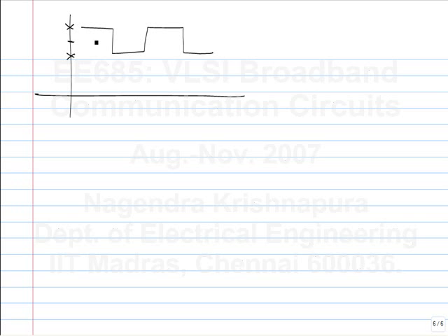Okay, that tends to also increase the error. So what you do is, in this case, you would rather keep the coefficient constant, and you achieve that by averaging this sign of e and sign of x. Only if sign of e and sign of x is constantly positive, that means the accumulated value will keep ramping up and hit a certain threshold. Only if it hits that threshold, you decide to decrement the coefficient. Okay, similarly on the other side.